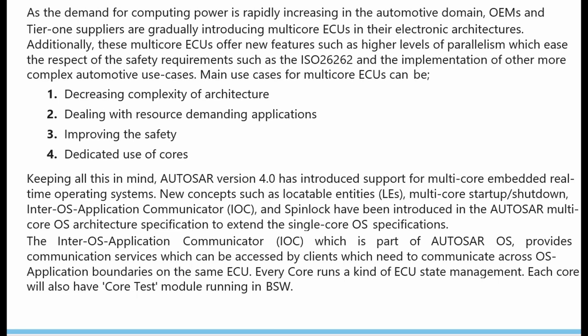Additionally, these multi-core ECUs offer new features such as a higher level of parallelism, which respects the safety requirements such as ISO 26262, which is related to UDS, DEM and DCM, and the implementation of other more complex automotive use cases. The main use cases for multi-core ECUs are decreasing complexity of architecture, dealing with resource demanding applications, improving safety, and dedicated use of cores.